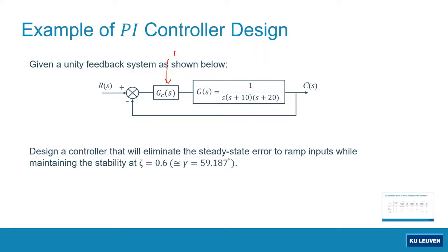Let's just start from scratch. We have put the system G(s) in a unity feedback form, but we haven't tuned the controller. So for the time being, let's just consider Gc equal to 1. In that case, this unity feedback system obviously is a type 1 system, right?